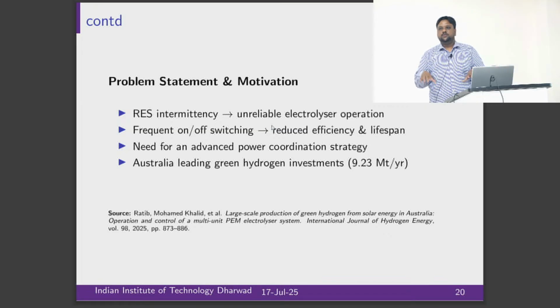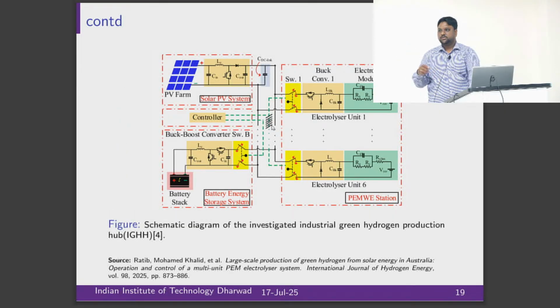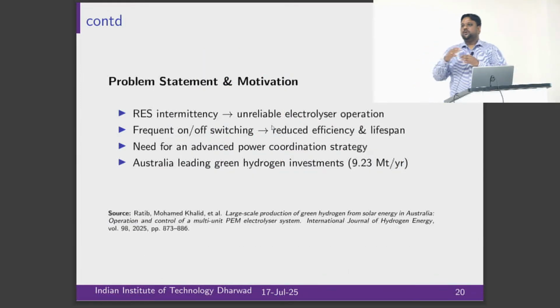Because with parallel electrolyzers you have to operate coordinately, each electrolyzer with some kind of protection strategy, right? Because power electronics are involved. If you see in the model, power electronics like a buck converter, single stage buck, are involved. Let's say one electrolyzer has a maximum limit or lower limit. The protection scheme works like if you hit the limit, you switch off, right?